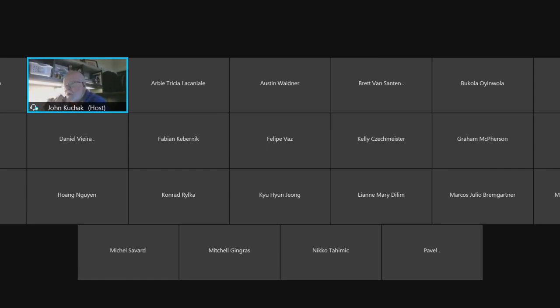Now, what you're going to find out, and what actually happened in the previous labs, is you're designed for 40.5 MPa, or say 40 MPa. And most of the students' mix design strengths came in at 42, 40, 43. You've met the city criteria of 32. No problem that way, by almost 10 to 12 MPa. But why didn't you get about a 7 MPa cushion on 40?